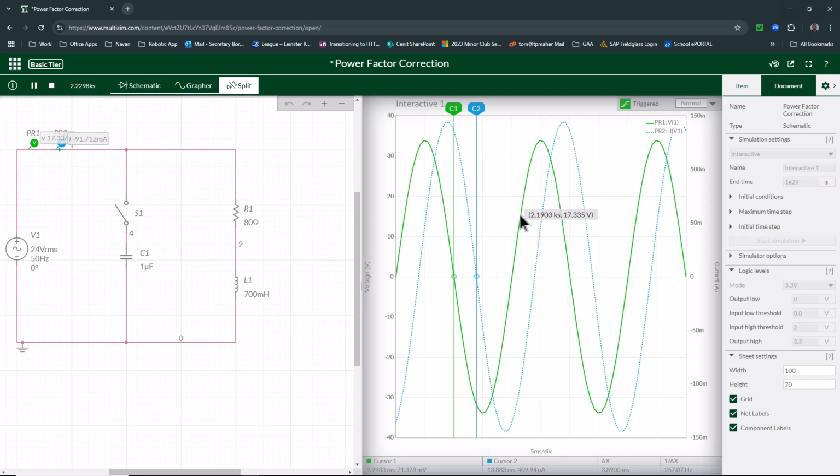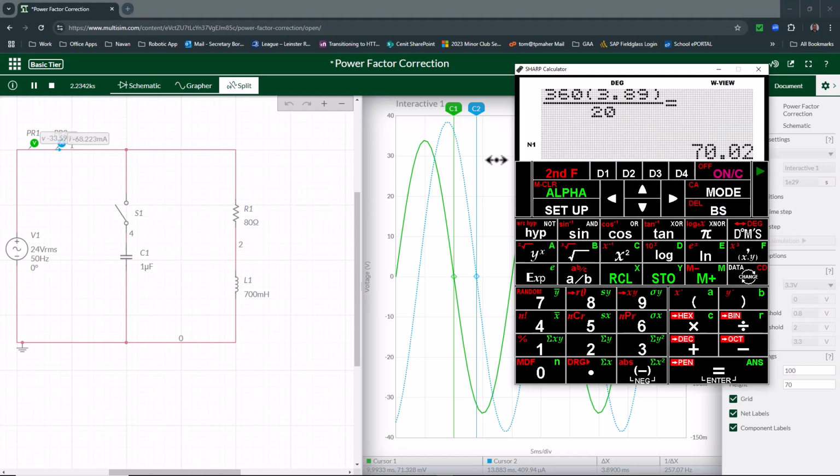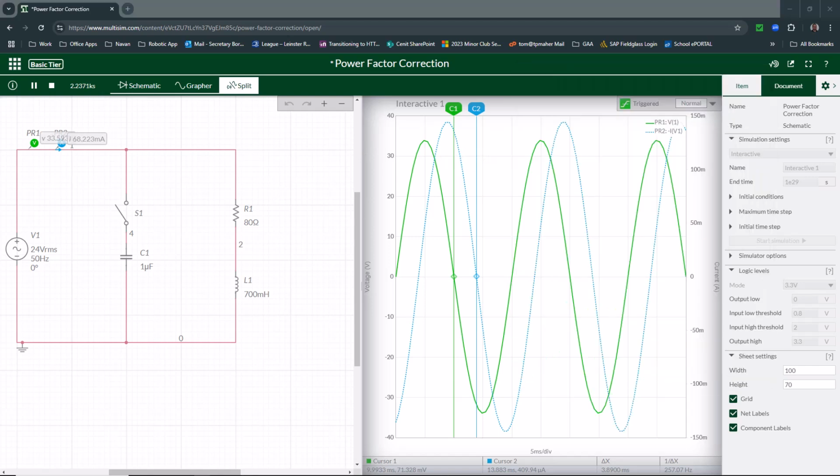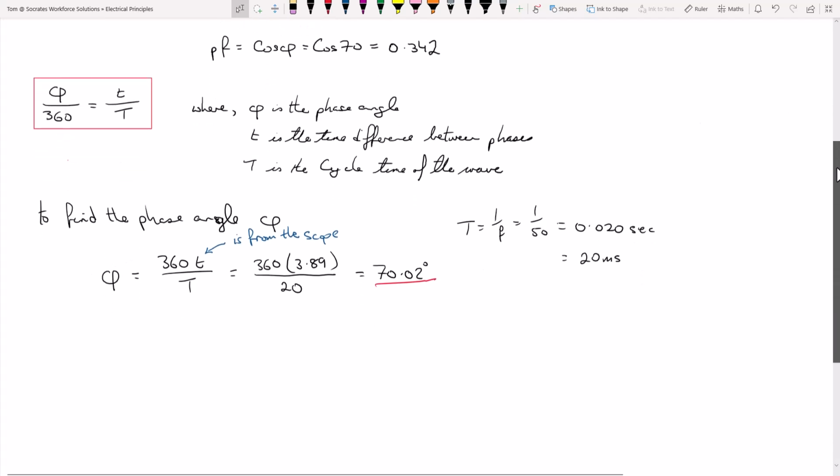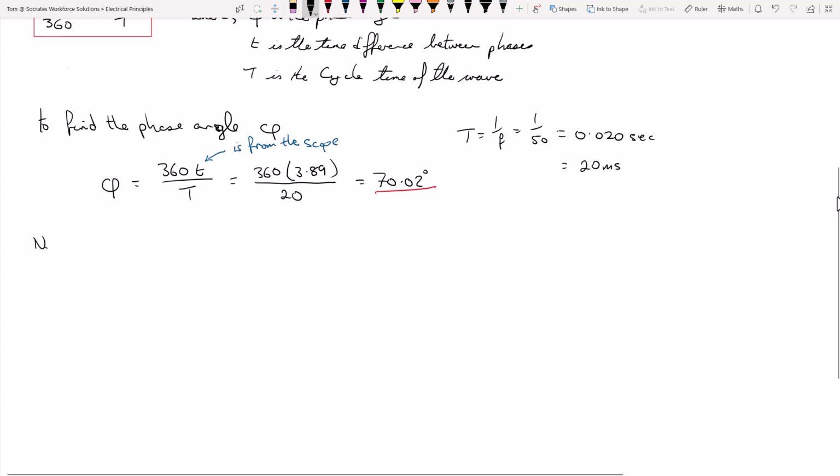All right. The next step, now that we have that system, would be to go away and calculate, given the new power factor that we need, what capacitor would be required. Okay, so we just grab the notepad here, and we'll scroll down a little bit. We're looking at a new power factor, which we call PFN, of 0.95, our classic one that we want to recalculate back to.